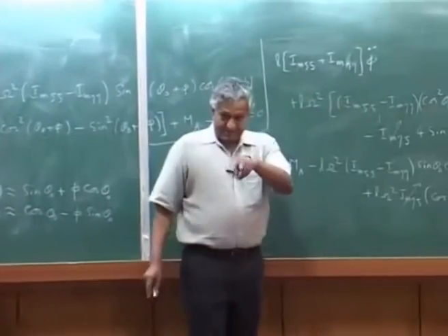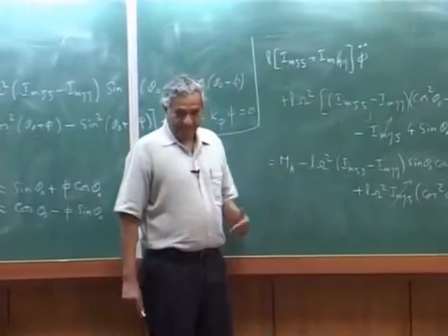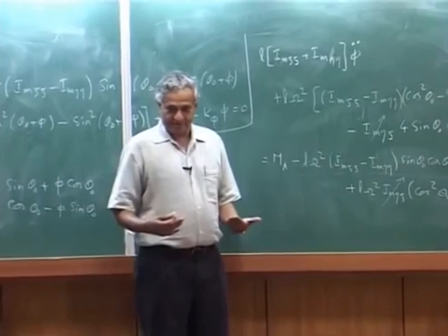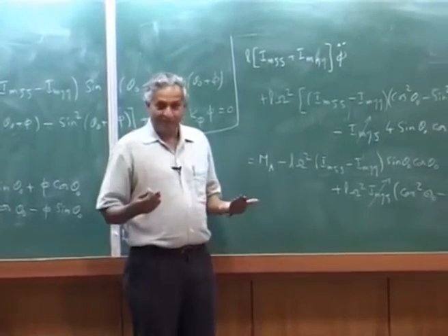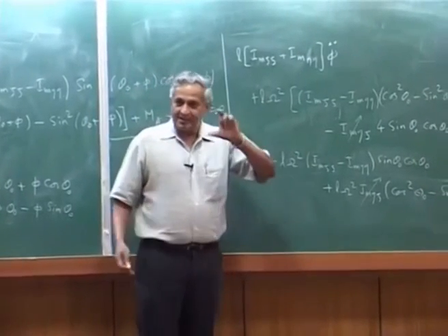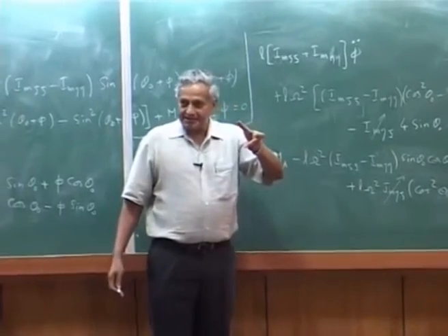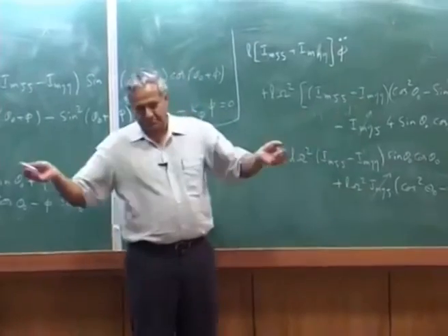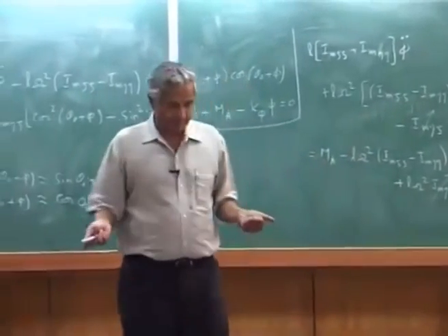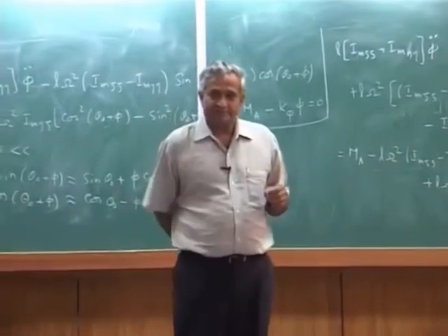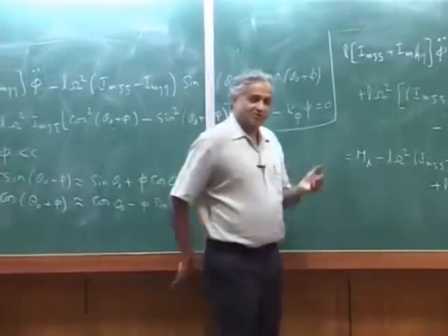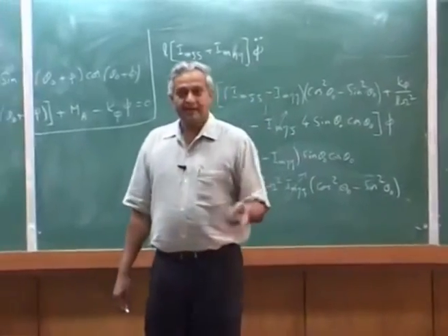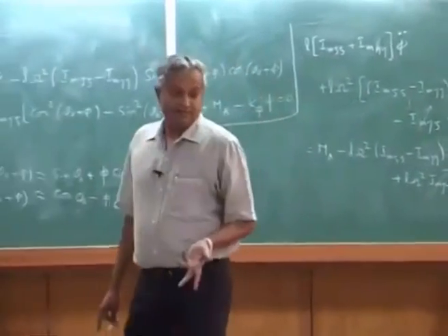Now you see the assignment which I gave. When we rotate it at a higher RPM, you can have an elastic twist of the blade due to control system stiffness plus maybe the blade elastic stiffness. There is a nose down. One can actually reverse calculate what should be the k phi, assuming that this must be my pitch angle.